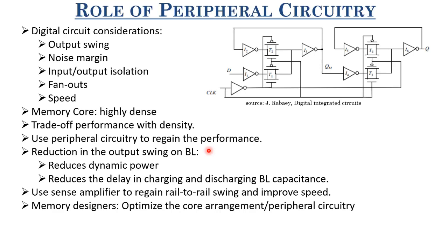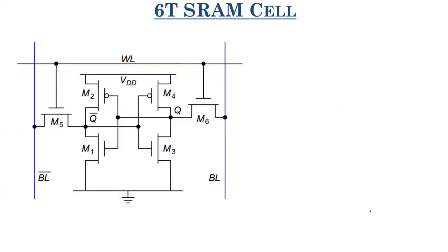Now, this is the major role of memory designers. Many of you may be going to memory design companies, and there the main role you will be doing is optimizing the arrangement of the memory core, as I discussed, like your aspect ratio, the decoder design, the sense amplifier design, your drivers design, and all those things. You would also be playing with these peripheral circuitries to further improve the performance of your memory blocks, which is a 6T SRAM cell.